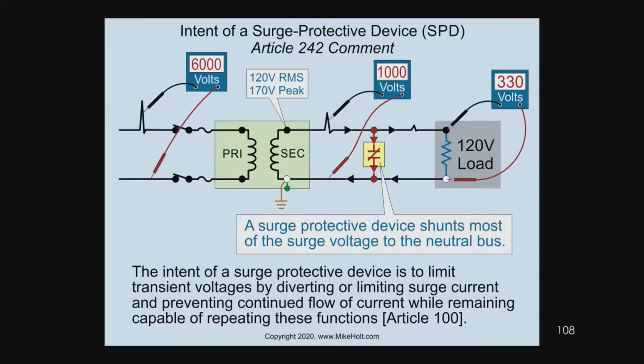So now that we know about transients, because of that energy going inside there, it's only supposed to be rated 120. They didn't plan on having it more than that. Now you get 1,000 volts. So now they get something called a surge protection device. Now, Jacob, let me explain it a little bit, and then John's going to get a little bit more inside here.